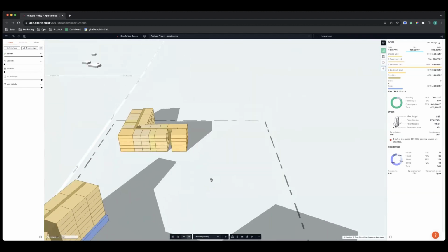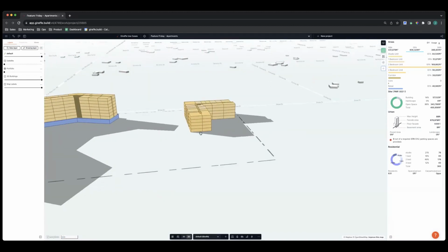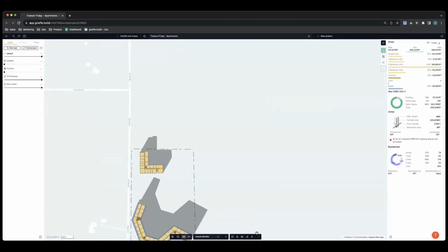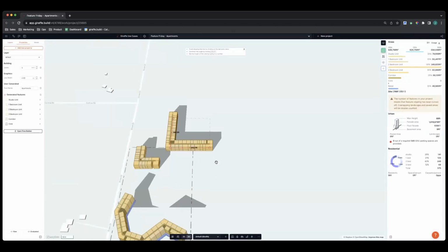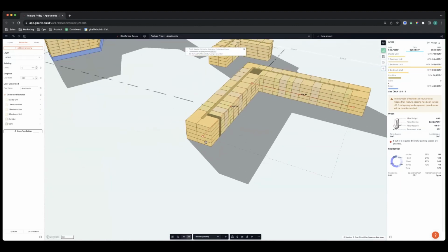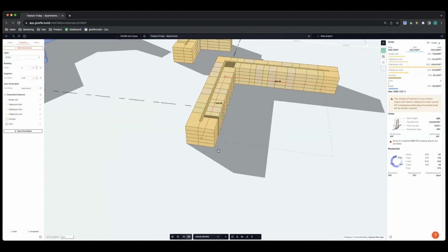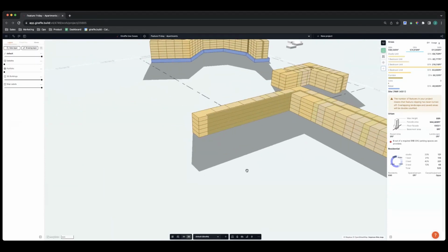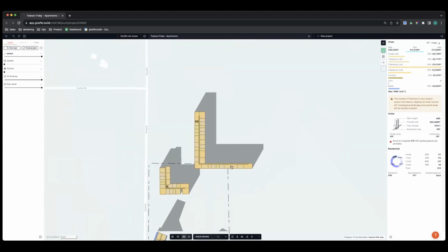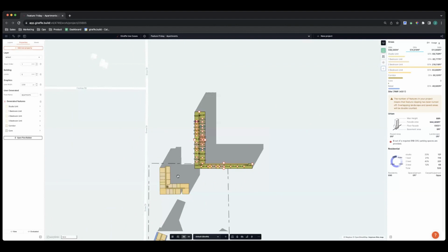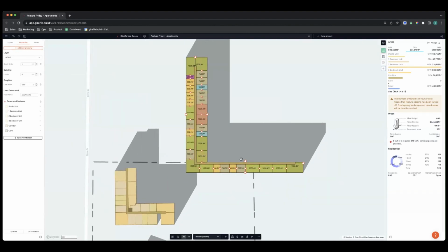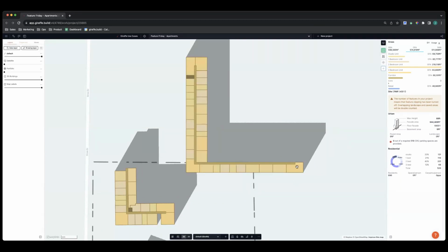So then the two other questions I get on algorithmic manipulation is, okay, that's cool, James, but I want to do something like an external hallway. How do I do an external hallway? So if I go back to drawing another algorithm, I can simply get rid of my double loading. So you see how I just got rid of the double loading. And if you hit Shift A when you've got this selected, instead of getting rid of one side the whole way around, I can actually just choose which side I want to get rid of. So I've just gotten rid of this loading here just to show you both.